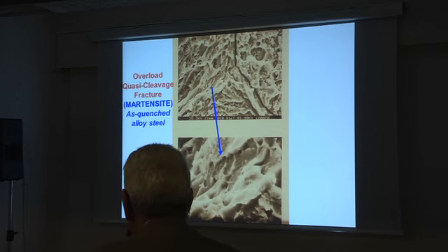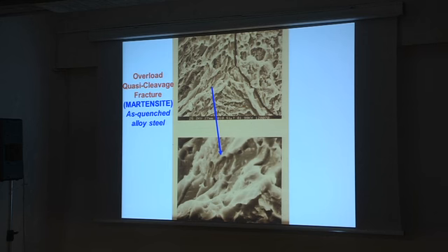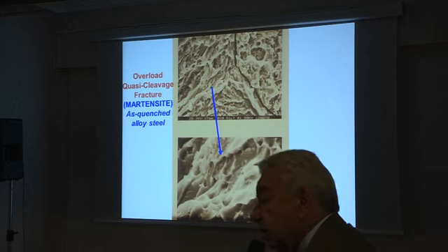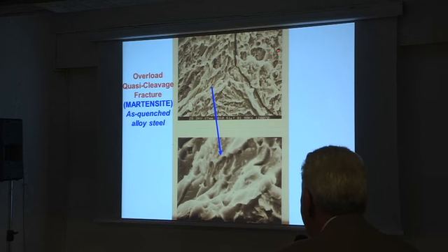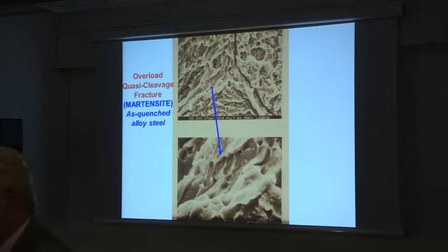And you can see that if the fracture is on this plane, which means that the maximum principal stress is perpendicular to the main fracture surface, and it broke by mode 1 separation in the direction perpendicular to the fracture surface, you have also the action of other perpendicular stresses, because you always have a tridimensional state of stress, and the other two were also strong enough to cause an initial separation along these, the boundaries of